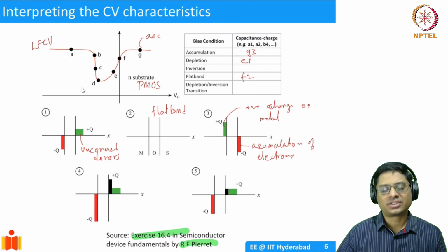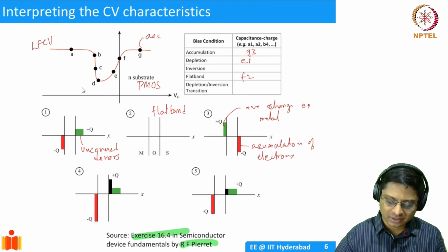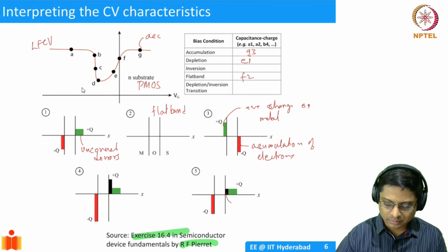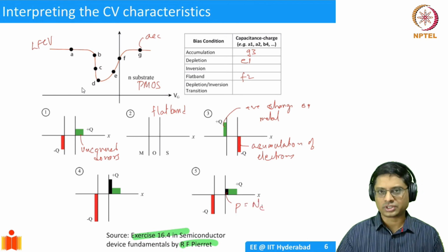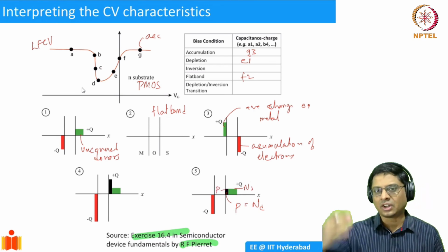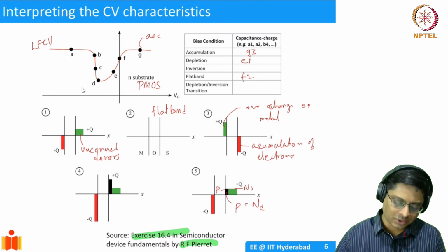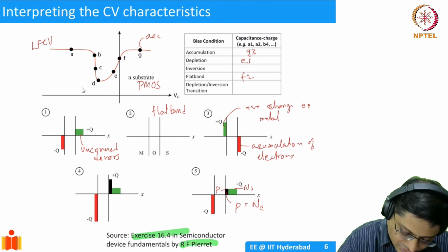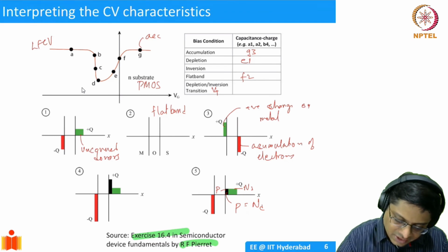We are taking an n-type substrate, so hole charge, inversion charge, the number of holes, p, is equal to Nd, the donor charge in the substrate. See here, this is Nd, and this is the number of holes, so they're equal. That's the onset of inversion, so threshold. This is called the depletion to inversion transition, or VT, threshold. So this is going to be D phi.